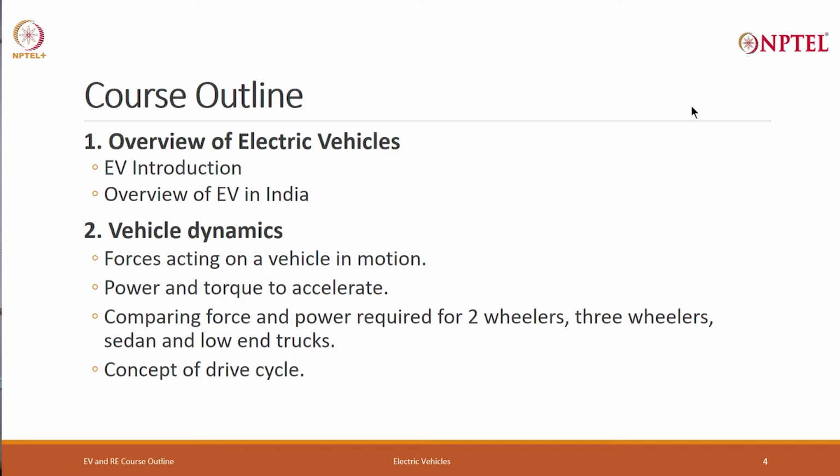And here we will start with, if there is a vehicle, whatever its size and weight, and we know it is moving at such speed, what are the forces acting on a vehicle in motion? That is the beginning, the first part. We will specifically look at any particular point, what is the power that is used to drive that vehicle and what is the torque required for acceleration.